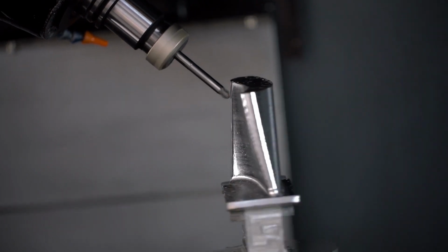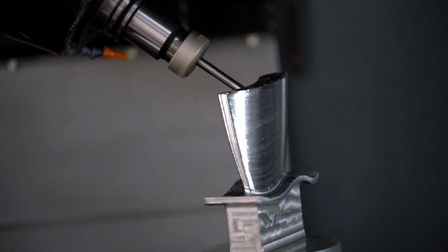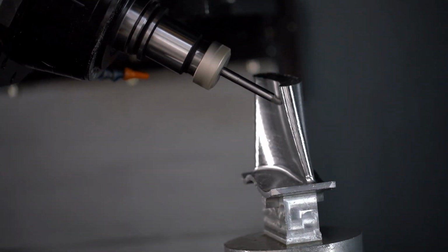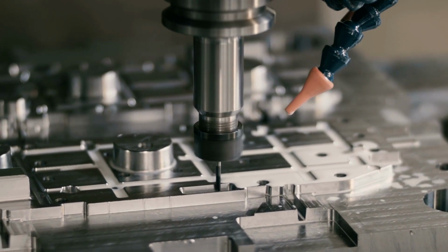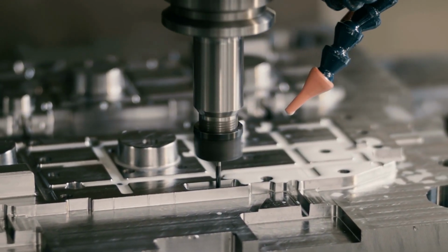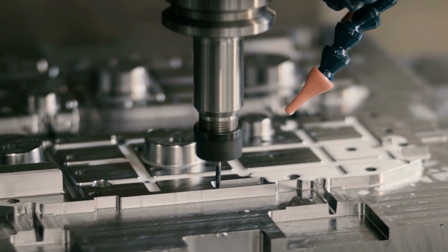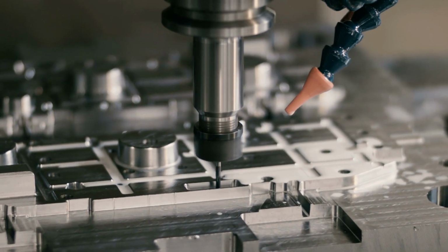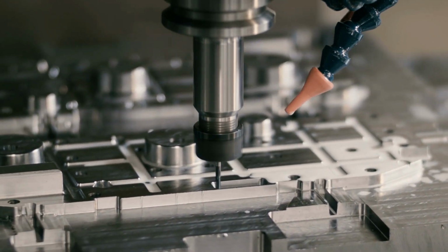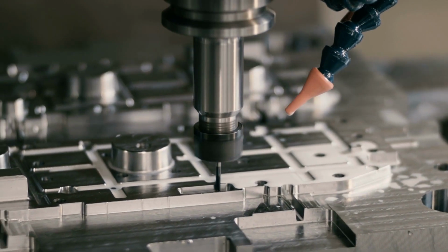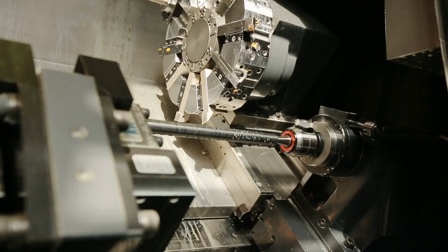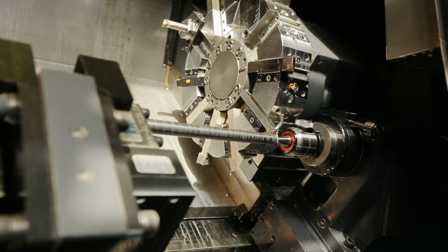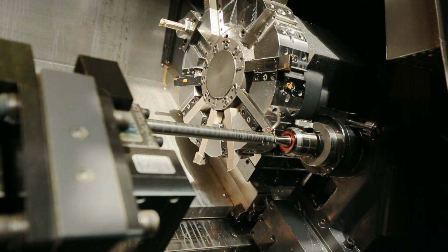Under the hood, the process can vary from machine to machine. For some machines, there is a physical limit switch that signals the controller that a machine has reached an axis limit. On some machines, there's an entire servo system in place that makes this entire process incredibly fluid and precise. A machine controller sends a signal through a circuit board to a servo motor, which connects to each machine axis. The servo motor rotates a ball screw that's attached to the table on your CNC machine, making it move. The back and forth movement of the table communicates coordinate changes instantaneously within accuracies up to 0.0002 inches.